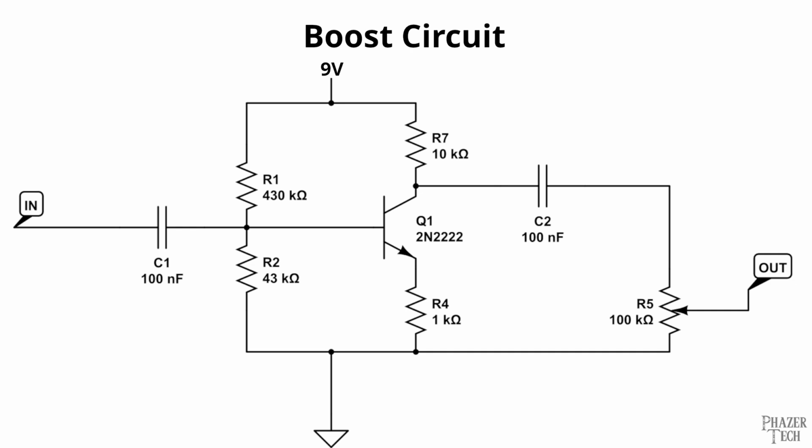Let's now look at a schematic for a simple guitar boost pedal. In case you're not familiar with guitar pedals, a boost pedal is used to increase the volume of a guitar signal before it goes into the amplifier. A typical electric guitar pickup will only output a few hundred millivolts, which isn't much, but a boost pedal can be used to amplify the signal up to at least several volts.